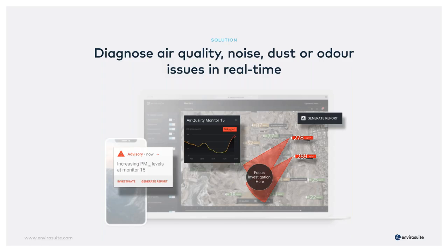Alerts can actually be set up on a case-by-case basis and can include several conditions. For example, if the wind direction is coming from a specific direction and the threshold exceedance is measured continuously for more than 15 minutes, then inform the operator so that they can actually take action. And this would allow the alerts to be tailored to site-specific management plans and unique meteorological conditions that are encountered in your area that would impact your local communities.